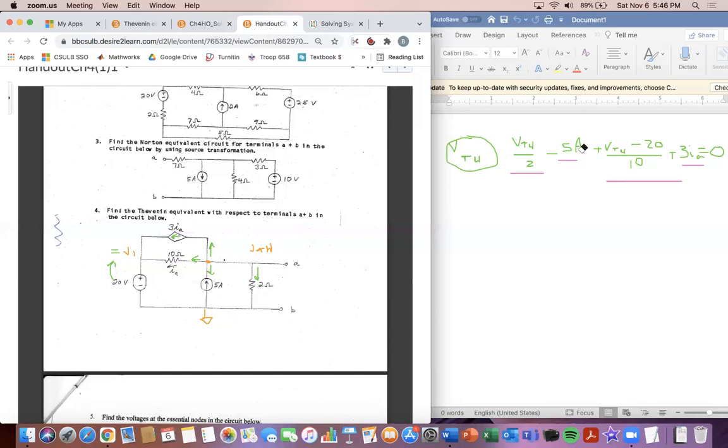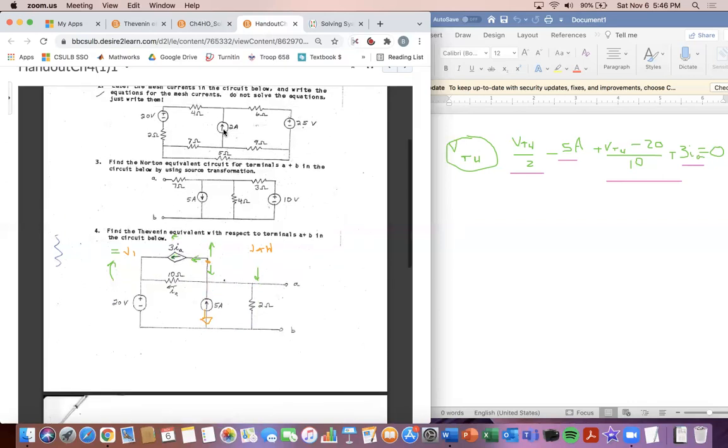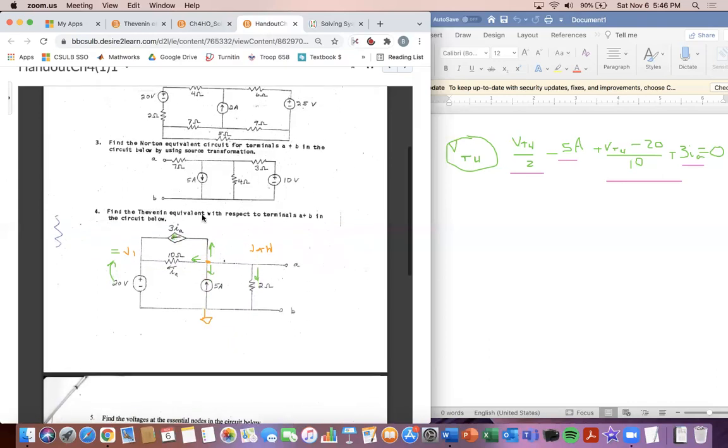So look at this equation here, everyone. We have one unknown, VThev, and we have a second unknown, IA. So let's write an equation for IA, because if you remember up here in this example, we made an equation for the 2 amps. So we can make an equation here for IA. If you think about it, we have the voltage VThev and V1 on both sides, and a resistance. Voltage divided by resistance gives us current.